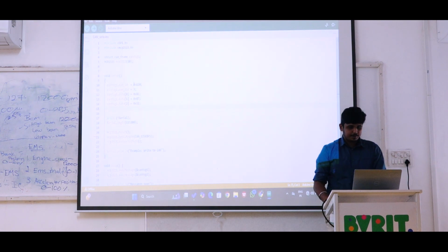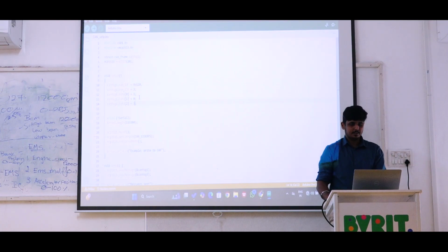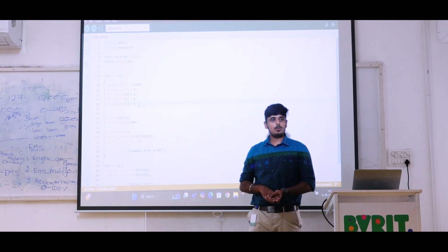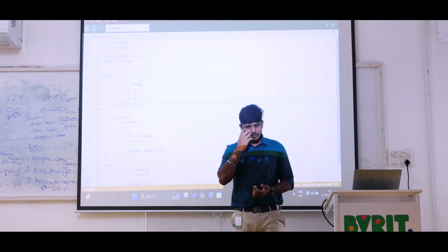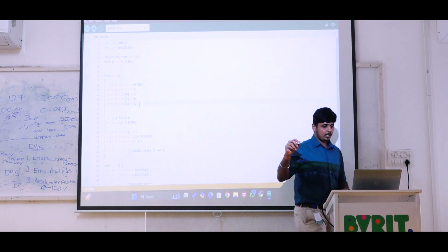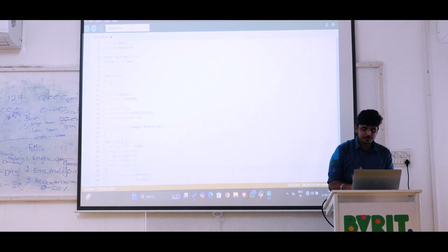3 things we are going to transfer. We set the lock signal as 1, unlock signal as 0, and tailgate signal as 1. In while setup, if you are using it, you can get only one-time data. For that, we need loop data, so we need periodic data. So we are going to copy and paste it in our loop section. Same data, I am just cutting here and pasting in our loop section.